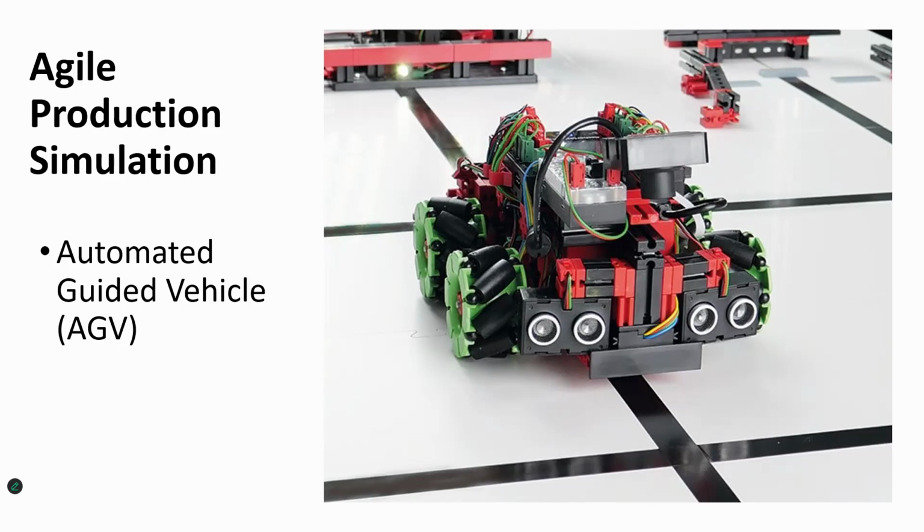Two buttons and a phototransistor on the vehicle help it to dock to the individual factory modules at their docking stations. The AGV receives its driving commands from the central control unit, which is an industry standard VDE 5050, and it uses a fischertechnik rechargeable battery pack as its power supply.